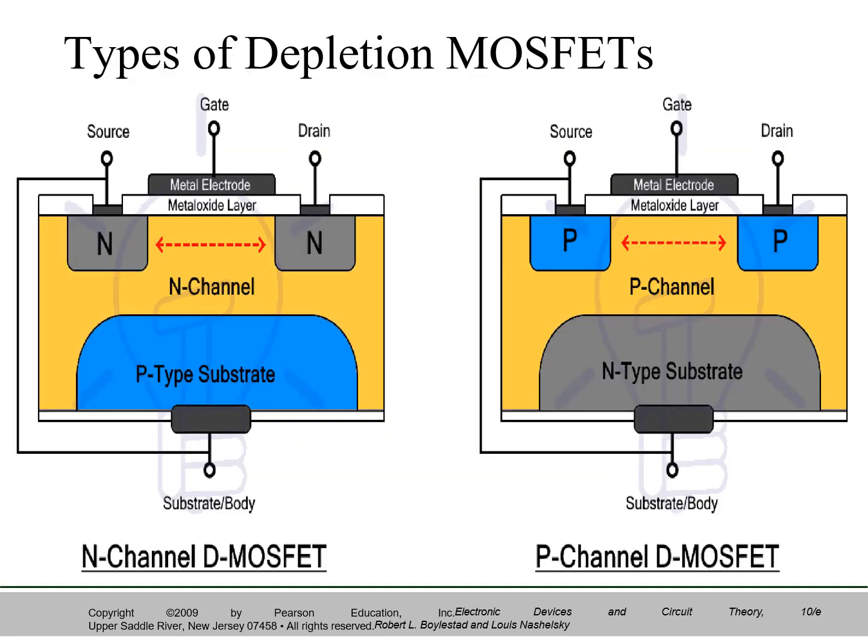Types of depletion MOSFETs: in JFET we have N channel JFET and P channel JFET, right? Same way, here in depletion MOSFETs we have N channel depletion MOSFET and P channel depletion MOSFET. Look at the constructional diagram here. The metal oxide layer is extra here, and that is where you have to be careful when you explain MOSFETs. A channel is physically constructed between drain and source here.